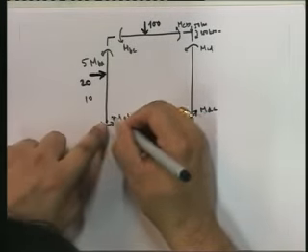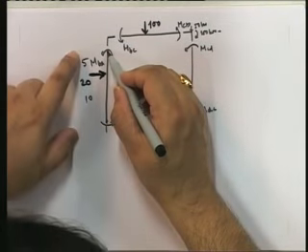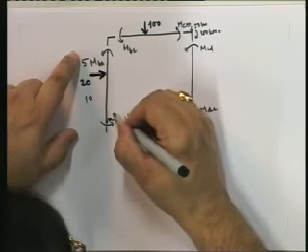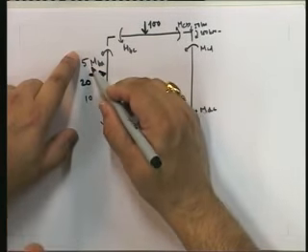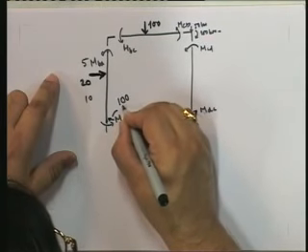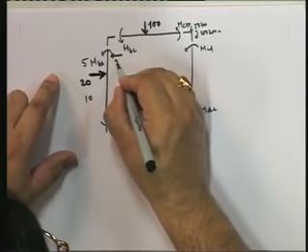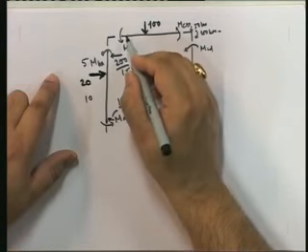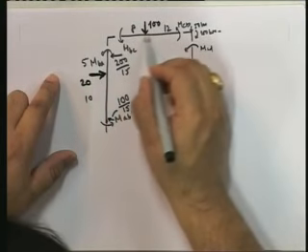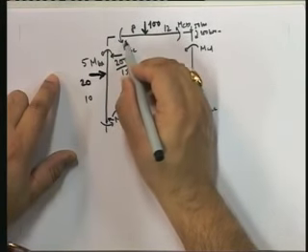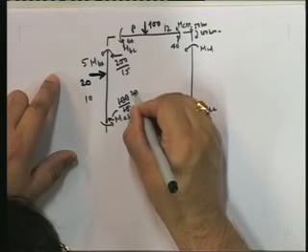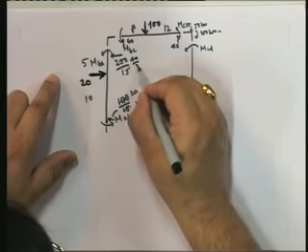So if I look at it, what is the reaction at this point due to this load? If I take moments about that point, you're going to have 5 into 20. This is going to be anti-clockwise, and if I put this in this direction, it's going to be clockwise. So this into 15 is equal to 20 into 5. This is going to be equal to 100 upon 15, and this is going to be 200 upon 15. Similarly, here we're going to have 8 and 12. Just due to the load alone, this is going to be equal to 1200. So this is going to be 60 and this is going to be 40. Of course, if I substitute, this is going to be 20 by 3 and this is going to be 40 by 3.